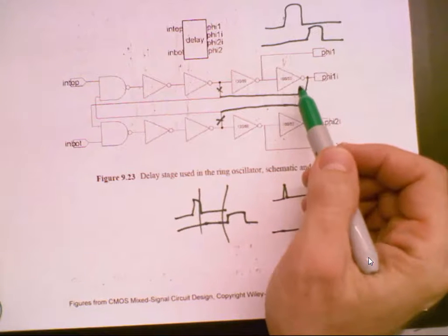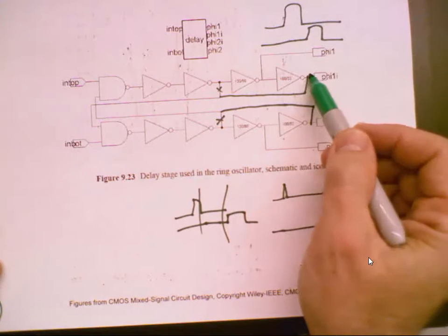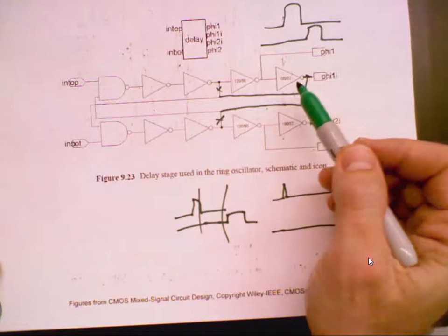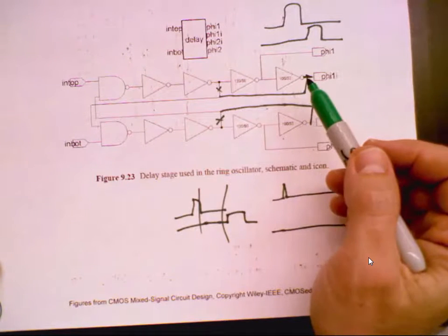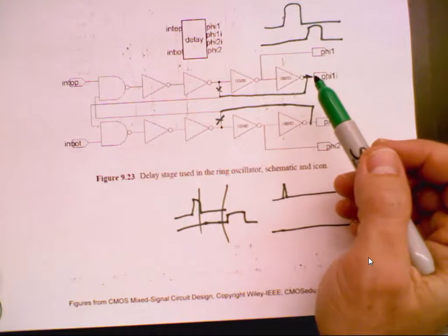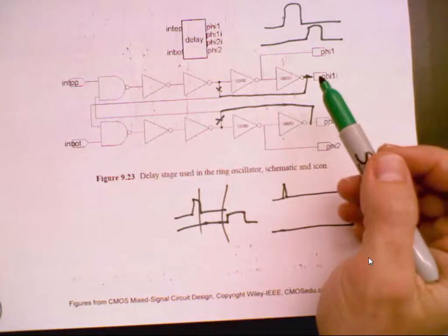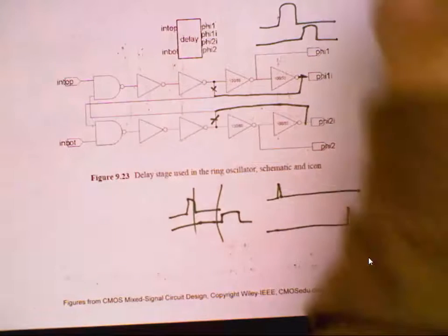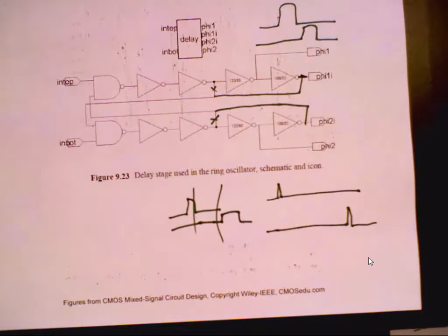But if I ask you, what happens to the delay and the 50% duty cycle? You say, oh, it makes the 50% duty cycle poorer. And I go, is that a problem? No, it's not a problem in my design. Why? Because I care about the edges between here and here, and this is what I'm feeding back. But I need to be able to ask you questions on that and know that you understand, unless you've not taken the circuits class, then I have to be understanding there.